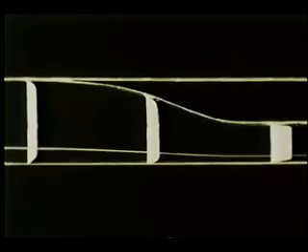The upstream boundary layer is growing slowly as it enters the contraction. After the contraction, the boundary layer is thinner. Note that the distance from the wall to the streamline downstream is about half what it is upstream, because the two-dimensional flow contracts 2-to-1. In the contraction, the effect of the pressure gradient in the boundary layer is to enhance the already high shear stress or vorticity concentration very near the wall.